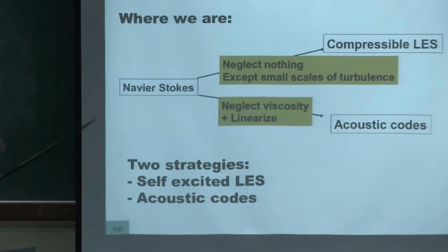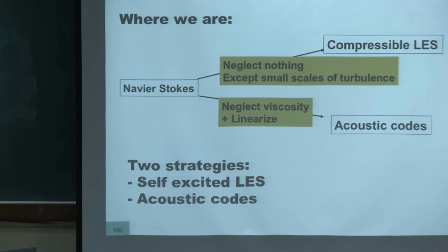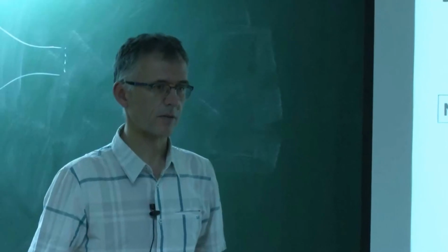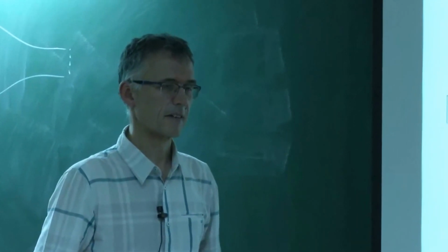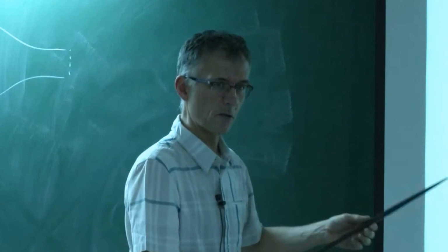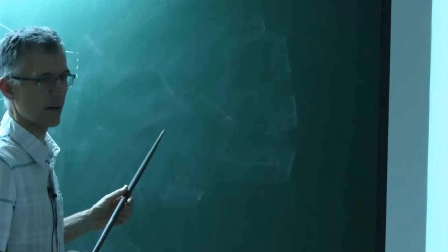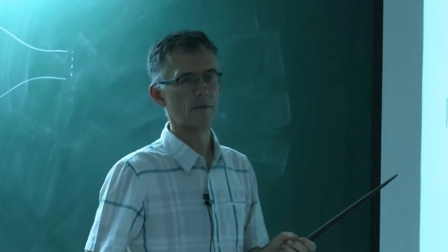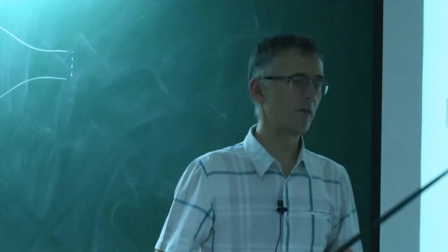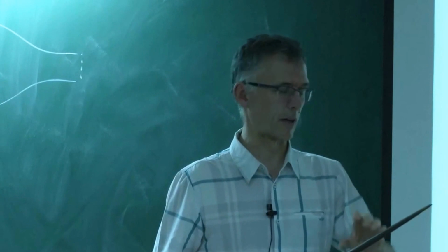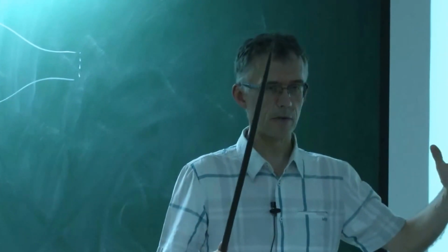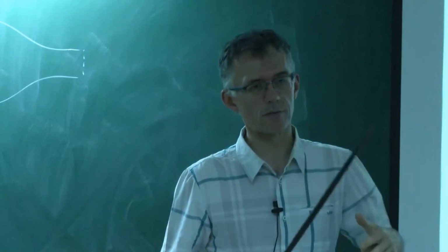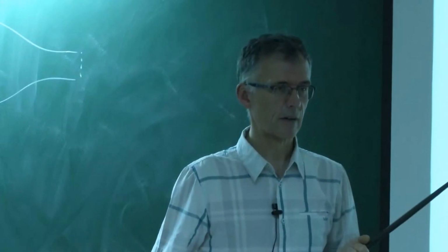So, how will you include this impedance in LES with the time-domain simulation? Exactly, you need time-dependent boundary conditions, and that's tricky. The other solution is to extend the domain sufficiently far to a place where you know the impedance. You will see, for example, for piston engines, what we did, we actually added a big plenum, and we computed up to the plenum so that we could say pressure was imposed. It's another way to do it.